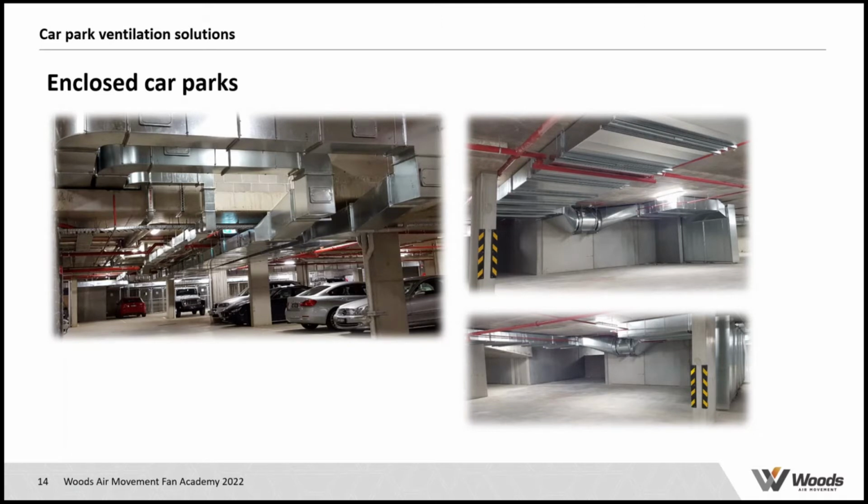And space in car parks is generally an issue, because from a structural perspective, you try to build a car park as low as possible, simply because that saves you a lot of money on things like excavation. But it leaves very little space for mechanical services, and especially ductwork is a nightmare in car parks because of this limited space. You often end up with duct design that is not ideal from an efficiency perspective.